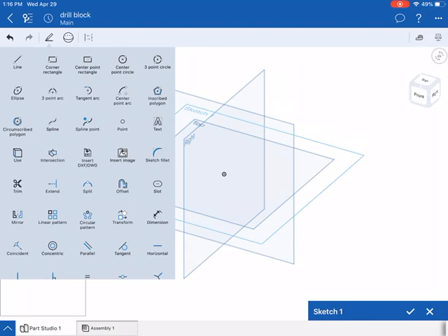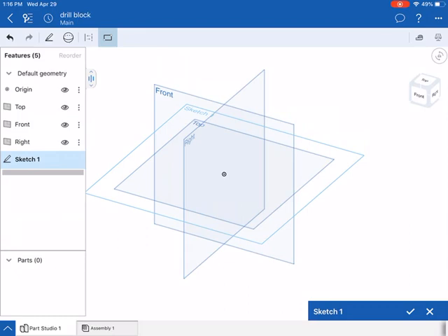And I'm going to start by drawing a rectangle in this one. So you can see at the very top, I've got my rectangle tool going on. The button next to the rectangle tool, the one to the left that's not highlighted, is where we can pick multiple things and put geometric constraints on objects. So to draw my rectangle, I'm going to draw the beginning point and the end point. So the two circles, just like you see on the screen, those are the two places I'm going to touch. It's not a touch and drag. It's a touch and then a touch in order to get your rectangle. So I always start my things on the origin. I want to put my first touch right there on the origin, and then I'm going to go out and hit again to create my rectangle.